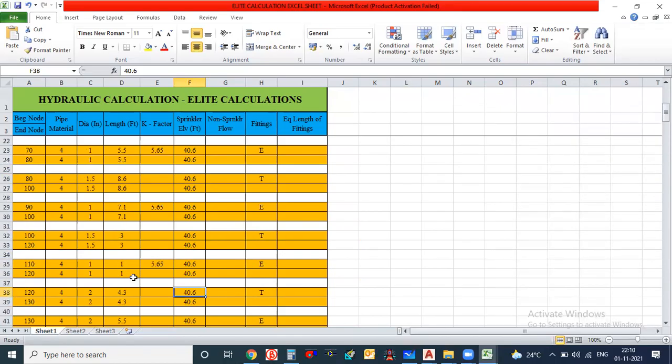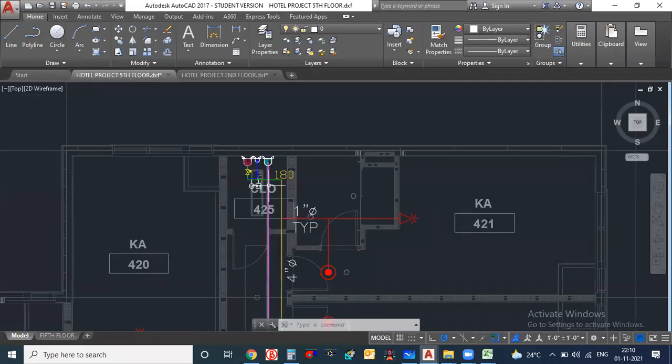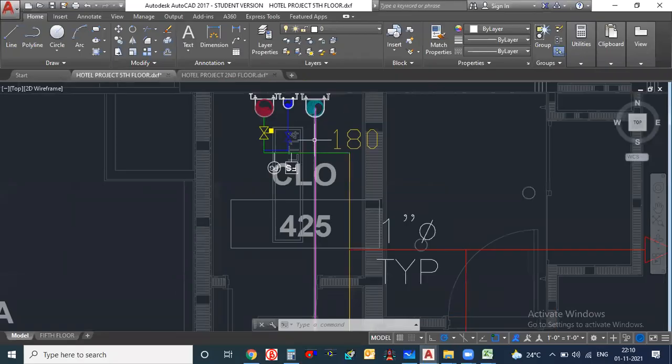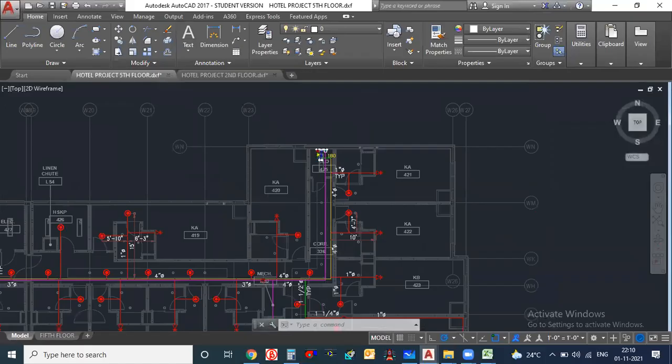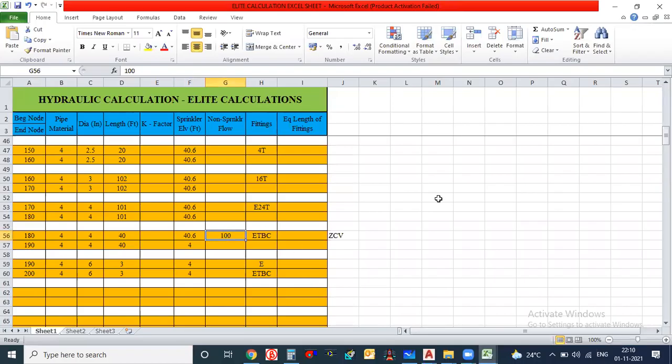Now here you see this is a sprinkler elevation. What is the meaning of non-sprinkler flow? It means wherever the hydrant is coming, you have to add the flow. In our example, I have added it at this point only, because I am expecting that this line is going to cross my sprinkler, or if it is not crossing also, no issues. I have to add the hydrant somewhere. If I don't add this hydrant GPM value, the hydrant calculation will not come.